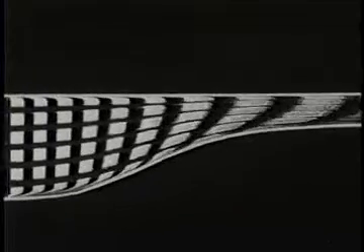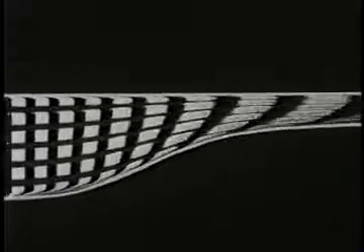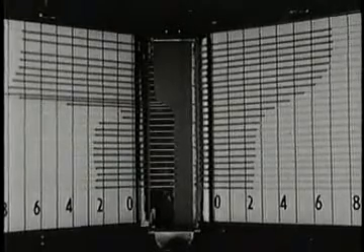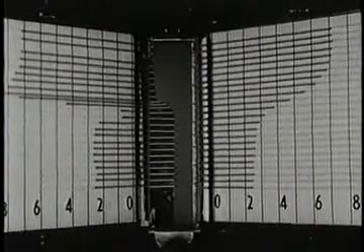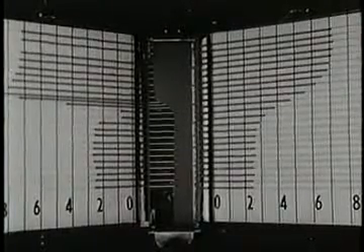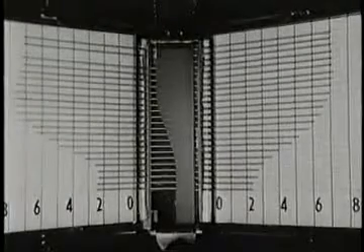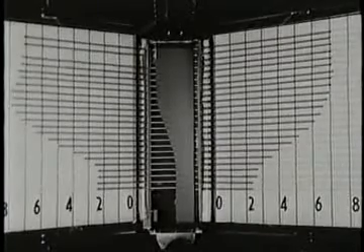To minimize adverse pressure gradients in wind tunnel nozzles, the contraction is made more gentle, as here. The streamline curvature is now much less, and the normal pressure gradients which caused the distinctive peaks in the pressure distribution are reduced. The flow is more nearly one-dimensional, and the pressure distributions on the two walls are more nearly alike.